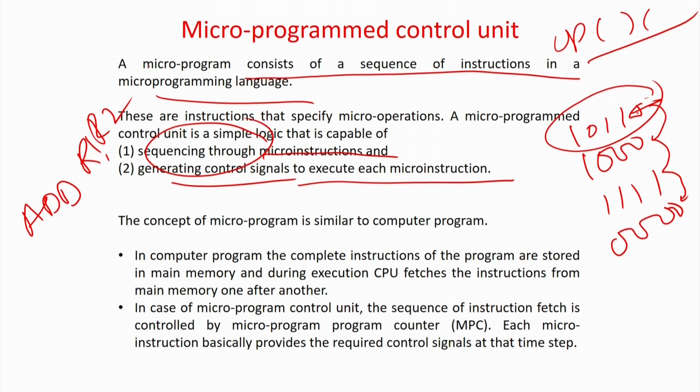So in that case, when it goes to the instruction register, you have the opcode and you have the operands. But in case of a microprogram, basically you have some bits and bytes. In fact these are also bits, but here we have opcode and operands and have separate meanings of different fields.